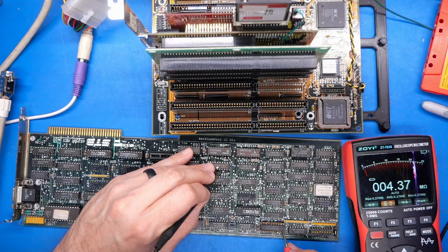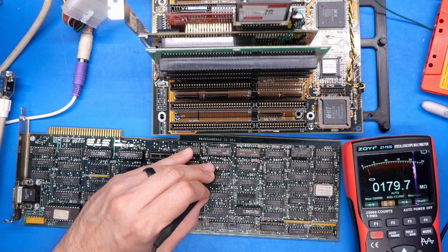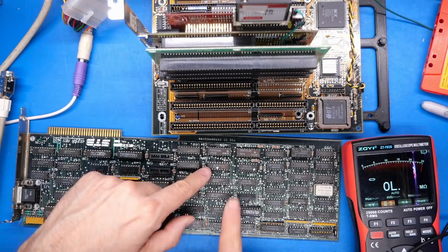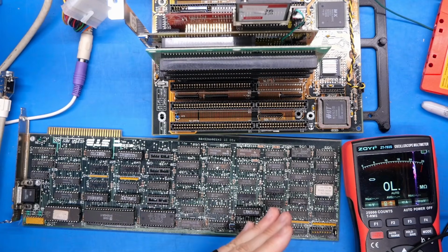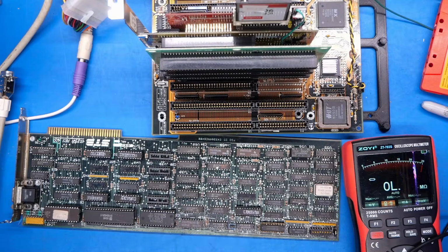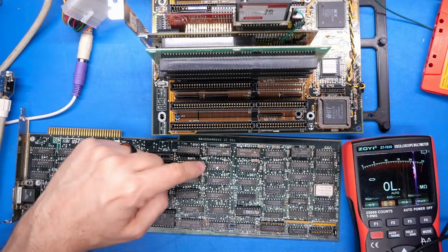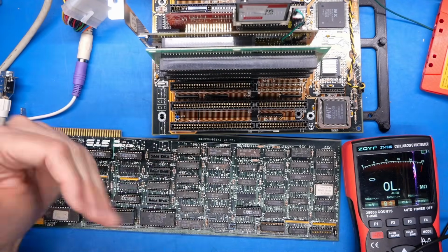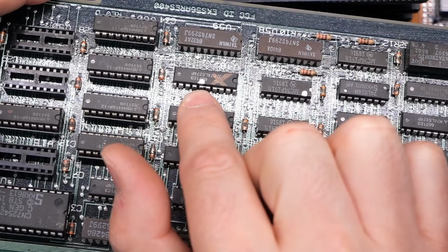Let's check one of the other pins. Same. So this is one of the working pins on the flip-flop, and to 5 volts and ground, we're getting that same exact megohm reading. I was just looking electrically to see if one of these was just shorted to ground, and it doesn't appear that they are. So that unfortunately doesn't really help us. The problem really could be either one of these two chips. It could be the output of the flip-flop, or it could be the input of this that's keeping it at ground.